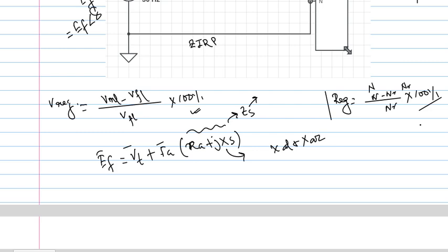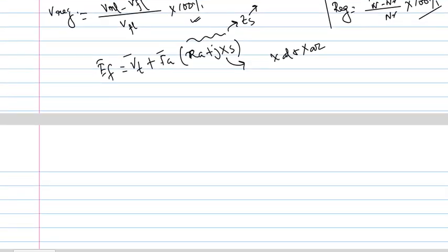Now gradually we move to the voltage regulation part. Many books define voltage regulation in many ways, but the standard definition is that voltage regulation is the change of voltage of an alternator if it throws off all its load completely. That means whenever it is running at full load or some load, and then the load is completely thrown off, how much the voltage rises or changes, that voltage change in percentage format gives you the voltage regulation.